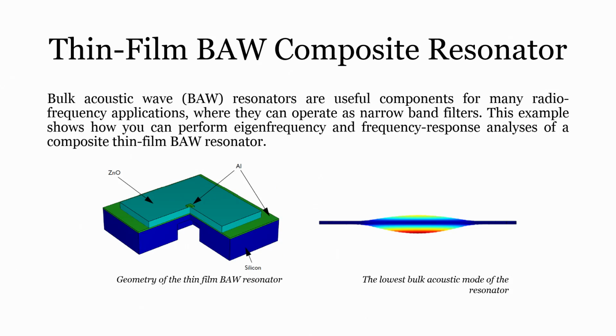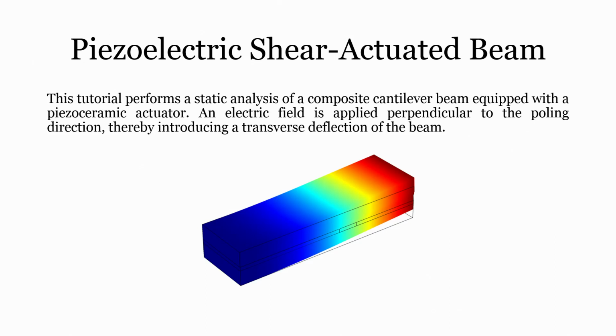We can also design and simulate bulk acoustic wave resonators, which are useful components for many RF applications, alright, in particular when they can operate as narrowband filters. We will discuss this in detail. We will also understand the piezoelectric shear actuated beam, and in this tutorial, particularly, a static analysis of a composite cantilever beam equipped with a piezo ceramic actuator will be taught.